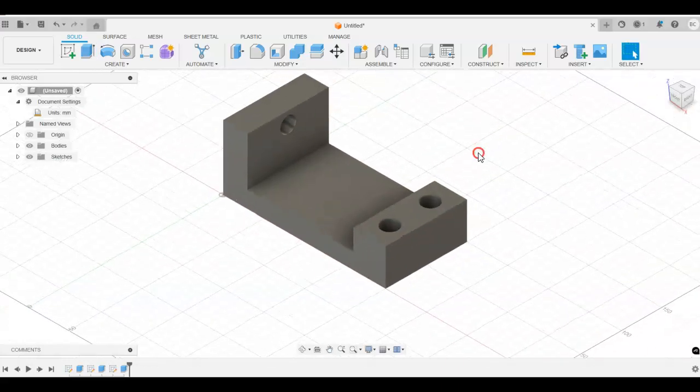Now we have added the two hole patterns that are on here just using the sketch where we're sketching a diameter or a circle on these and extruding down. So that is the holes adding into this particular product and model.